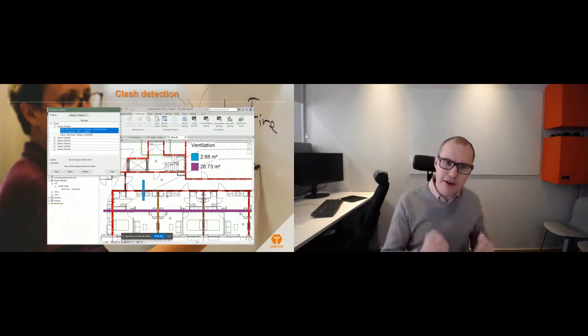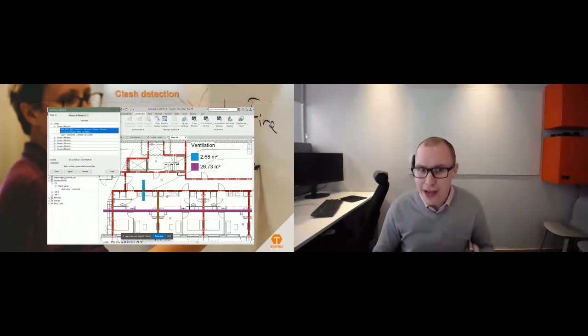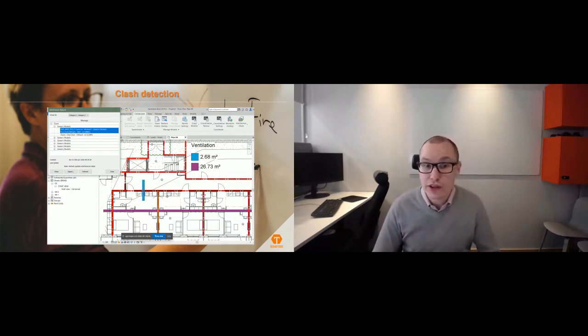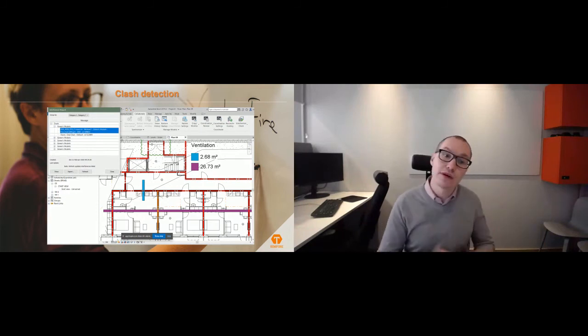So you can use the fire safety model to find and check all these kinds of penetrations and fix them basically in the design phase, before going out into construction. Usually they just look at the architect model and try to figure out where it is. Because it's just lines, in most cases we can't really check this automatically. But having a 3D model, we can actually use Solibri or Navisworks and have rule sets for just this.